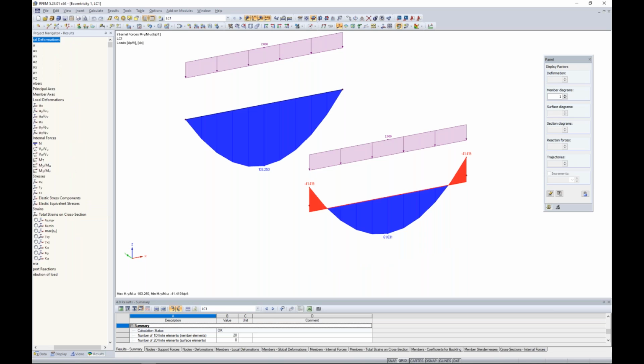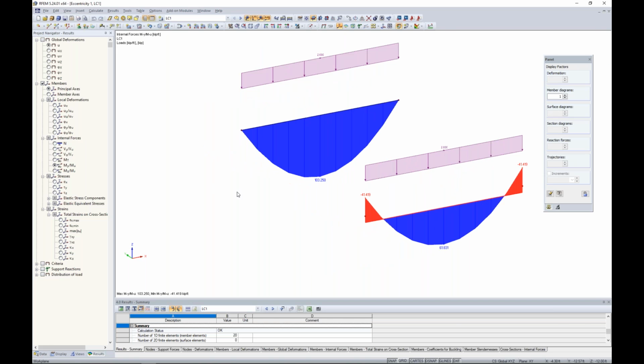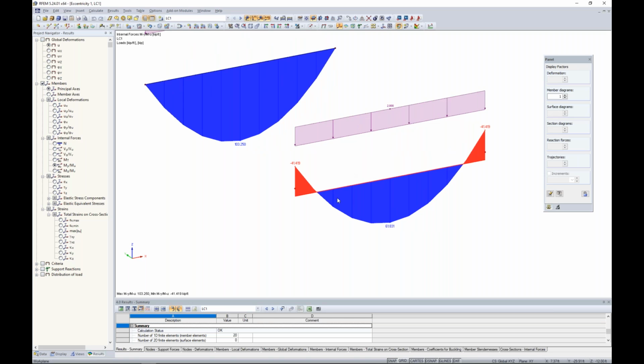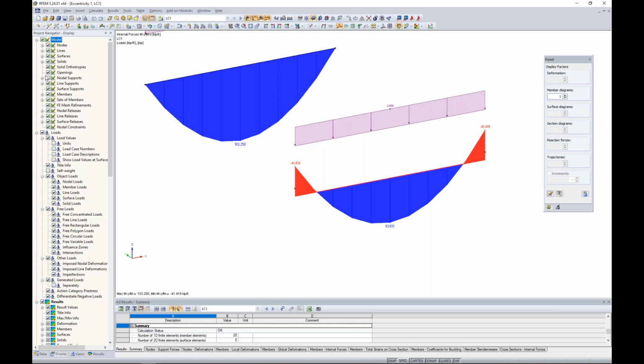And we'll immediately start off with the moment diagram. So, a simply supported beam, we take a look at our first example here. This is exactly as we'd expect for our moment diagram, peak moment right here at the center. But as we transition into those nodal supports, which are a pin roller type situation, we expect no moment. Well, by introducing this eccentricity here to drop the top of steel down to where our nodal support is, we now have a negative bending moment here due to those rigid elements at the end. Our peak moment here in the center is almost half of what we're seeing with our original beam element.